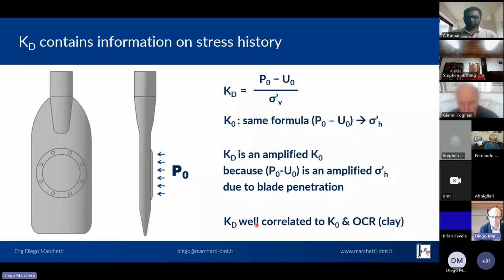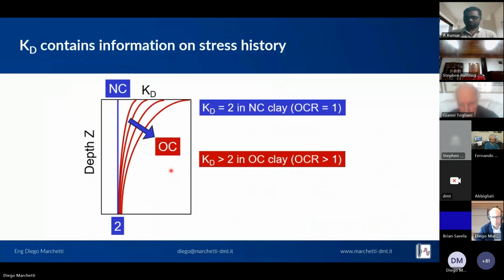However, we will see that KD is very, very well correlated to K0 and OCR in clay, especially, and that it is probably the closest measurement of K0 than any other method possible and faithful to the original state of the soil in situ rather than in laboratory.